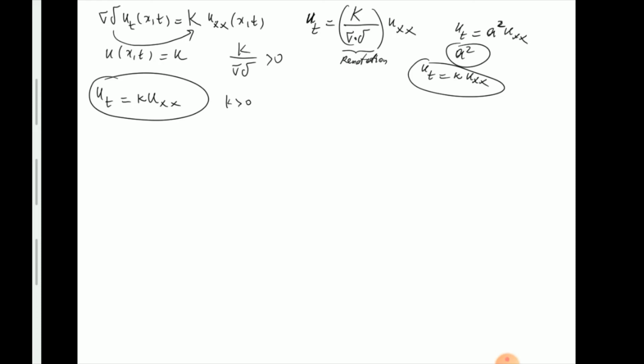What's important from this point on, again, is to remember, first of all, where it came from, because many boundary conditions are still given in terms of the flux. We'll talk about how we establish boundary conditions later in another lecture. So make sure you remember this formula as well, in addition to the actual heat equation in one dimension.